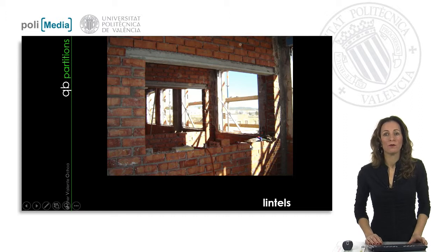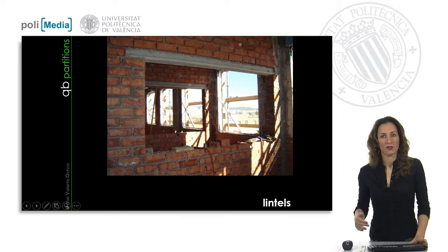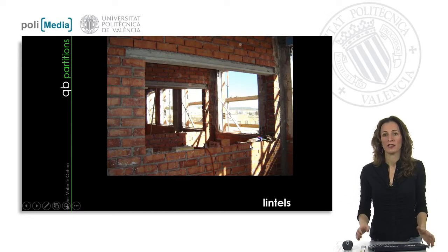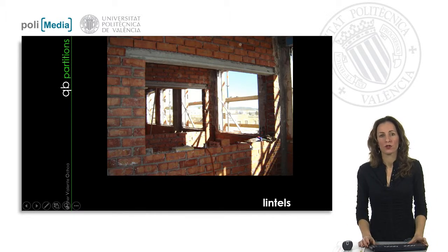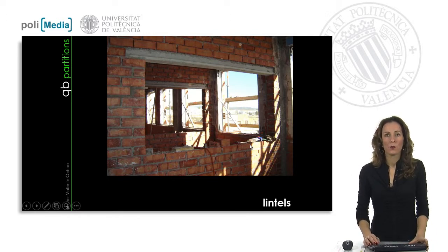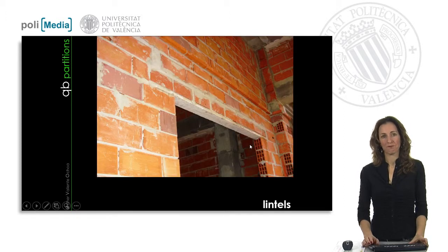Lintels could also be mandatory in the partition walls, not only for facades or external walls. In case we have any kind of internal carpentry or the distance is big enough, we will use the lintels as resistant pieces that will support the future brick rows we are building up on top. Some lintels like this one are built into our brick rows.